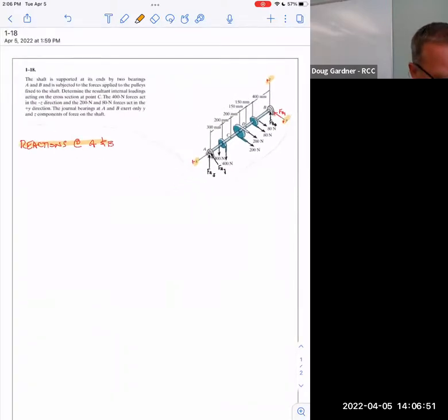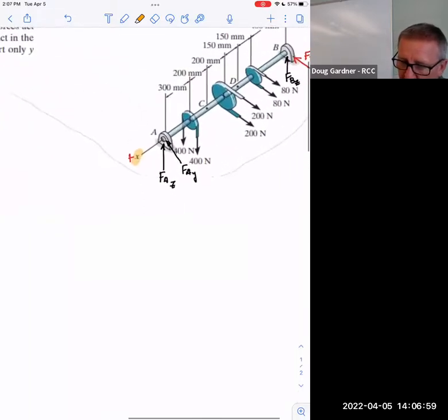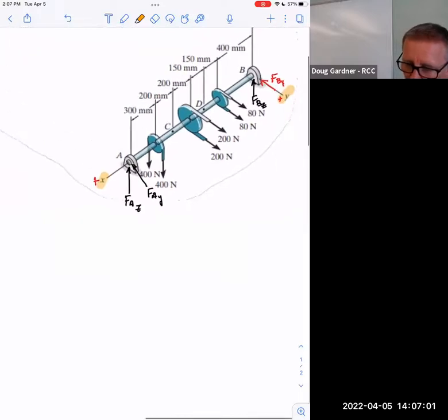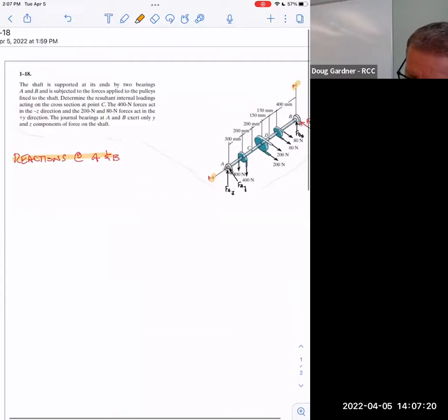And so let's see, how do I say this? Does it make sense I can't do the sum of the forces in Z? I just wrote it down. I was like, I can't do it. Why not? Why can't you do it? Say it out loud. Because I have FAZ and FBZ. Yeah, they're going to work together to defeat that 800, but because they're proportionally in weird locations to each other, just like before, I'm not going to be able to make any headway with that. I'm going to have to do some of the forces, some of the moments. And so let's try to do that.